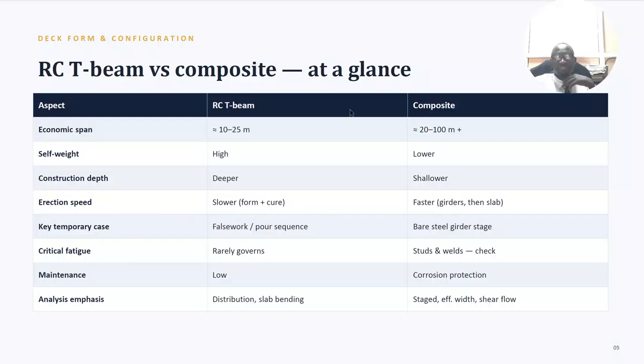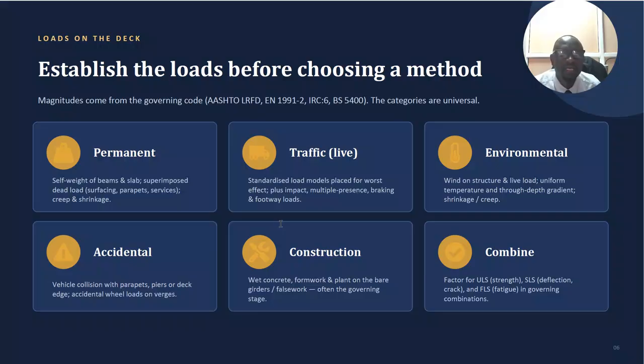So they are giving you the comparative analysis, but in every design you do, depending on the location, sometimes the location favors the composite over the RC, and therefore you have to go for it. In most cases, in flat terrain and easily accessible areas, you are better off using concrete, and there are other benefits. So you can see all here.